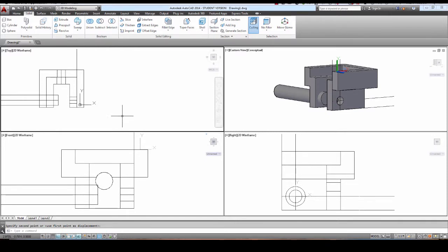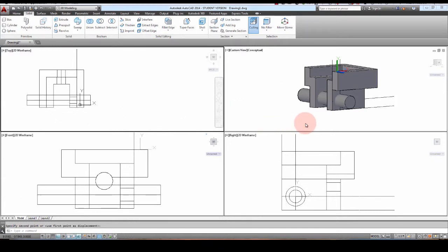Okay. So you always have to remember when you're subtracting something, it's overlapping volumes. It's the volume of the two objects. It's the volume of the cylinder and of this wall. It's inside here. That's where it's going to do the subtraction. So if that was actually going through, just to show you an example here, if this was going through both like this, it's just going to make this hole bigger over here, and it's going to get rid of our original first hole. So let's see that.